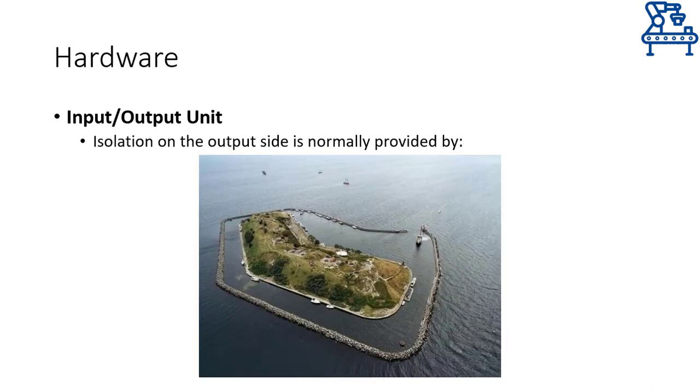Although input modules use optocouplers to provide isolation of the input module circuitry from the outside world, the output modules normally rely on other isolation techniques. The major reason is that for the input side, only the signal coming from the input device is required, whereas on the output side, devices require high voltages and currents. Therefore, isolation devices capable of switching high voltages and currents are used.